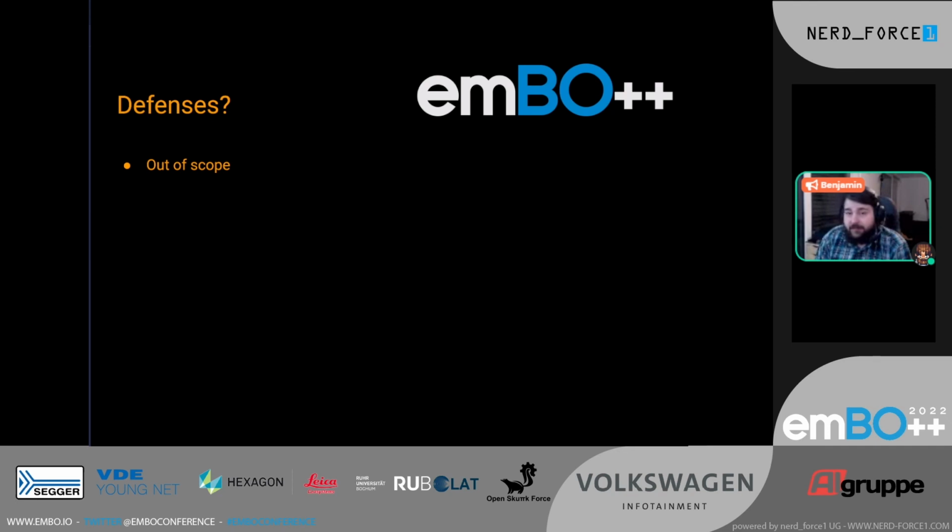But if you want to defend it, improving the accuracy of your brownout detector can be a good choice, because a brownout detector, if it reacts really quickly, will be able to detect our glitch attempt and reset the chip in response and return it to a safe state where we know everything is okay. But there's a trade-off. If your brownout detector is really sensitive, it might actually trigger a reset, even though it was a normal operating procedure. So take care to design it properly.